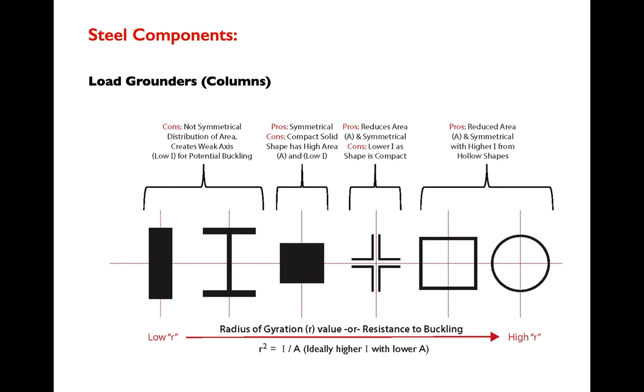We'd like to get to both sides of a steel element when we're bolting it together so that we can hold a nut on one side and put the bolt through on the other. There's no good way to reach more than a couple of feet into a hollow section to do this. And so even though there's a trade-off in terms of pure structural performance, very often we'll use compact section wide flange beams for columns, in part because we can access both sides of the web, we can access both sides of the flange, and this makes it easier to connect other elements to those columns.